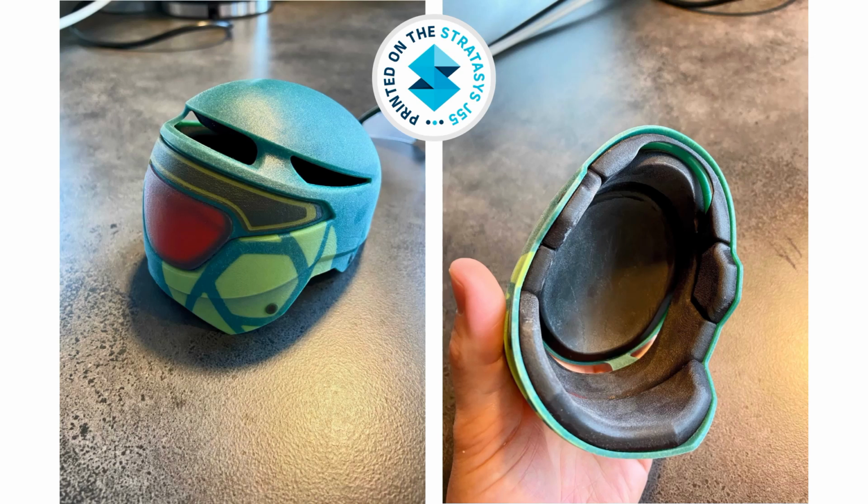Another benefit towards using KeyShot is that once you've applied all those materials and textures to your 3D geometry, you can export it out as a 3MF file. Now this 3MF file will contain the geometry data of your CAD model within there, as well as the colors of the materials that you've put on there, plus any textures and roughness.